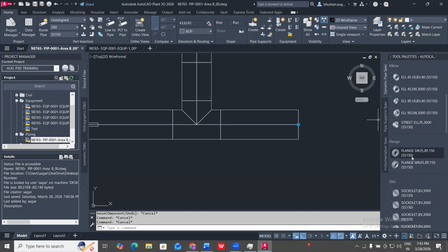So the fourth rule is the path angle must match, specifically for bends and elbows. If you have a 90-degree elbow and want to substitute it with a bend, it must also be a 90-degree bend, and the path angle must be the same.